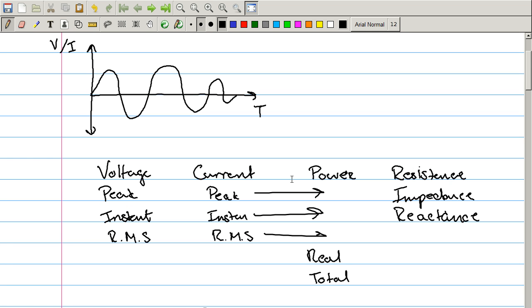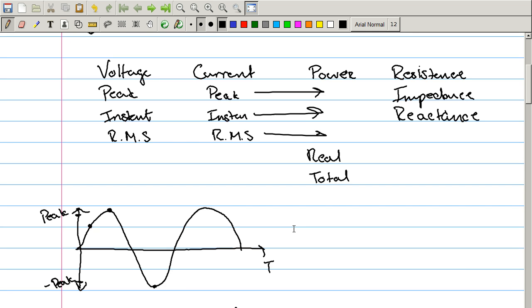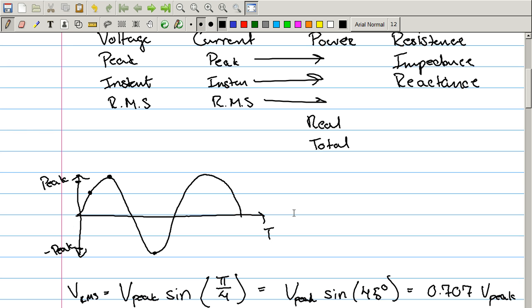So I guess what that just leaves is power. Now, the thing you have to remember about power is, again, if we're just going to talk about sine waves and cosine waves by extension, that they are periodic. Meaning that you're going to have an area of positive power and you're going to have an area of negative power. And if you go on to a time of infinity, what that will eventually sum out to is zero power.